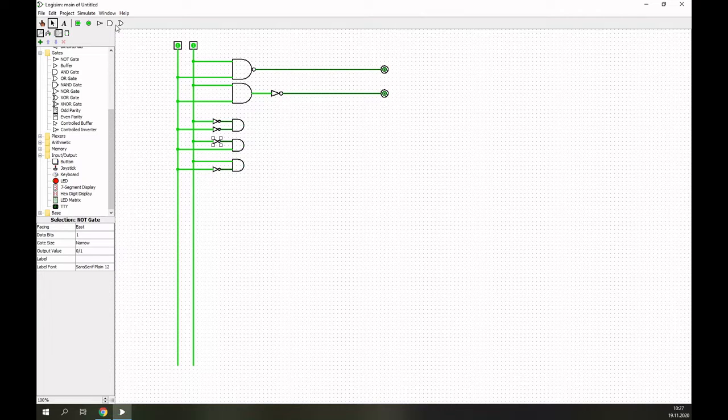And then we combine everything with an OR, with 3 inputs in this case. And then let's connect the output from here as input of the OR, and this is our new output. So this was the original truth table as we got it. So let's test if everything works. So 0 0, or either this, and only if both are on, then you have a not. So it's exactly the same, you see.